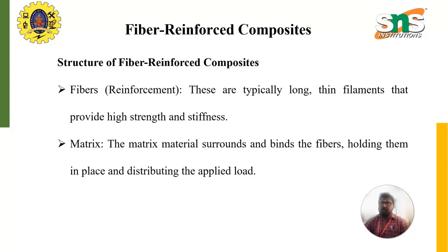Fiber reinforced composites are a class of composite materials in which fibers such as glass, carbon, or aramid are embedded within a matrix material. The fiber provides the composite with strength and stiffness, while the matrix binds the fibers together and helps transfer loads between them.